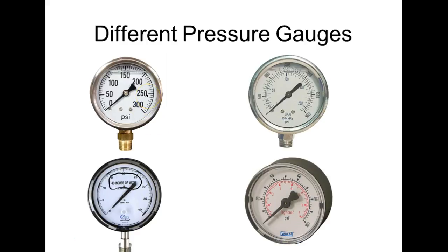In my infancy in these things, we got one of these gauges, and it looked like it was full of carbon. What's wrong with the gauge? It's got goop all in it. Y'all know what that is for? It's a dampener. It keeps the needle from vibrating. What is that? It's just a silicone-based compound. So it's a goop is what it is.